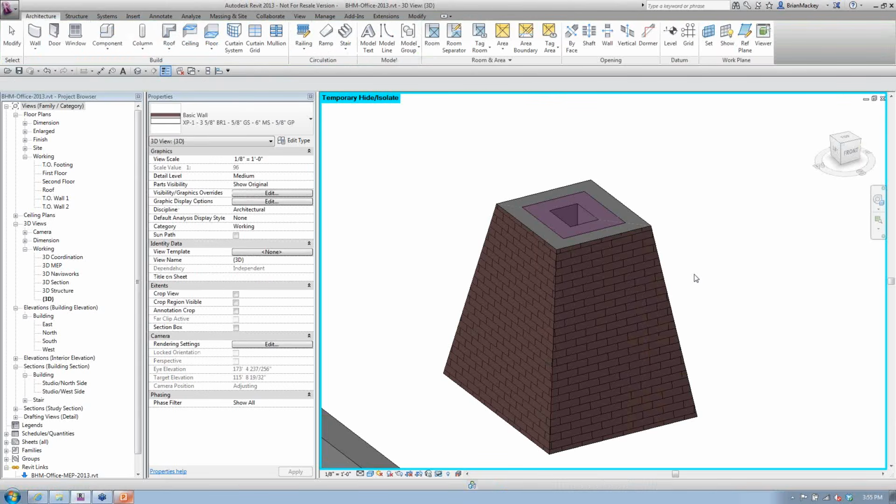And I could go model a structural column coming out of the middle of that. Okay, and Dale asks, if I go to town in Vasari creating masses, can I then bring it into Revit and apply walls, floors, roofs, etc.? Absolutely. So that's one nice thing: you're creating a mass family inside of Vasari, or even a project in Vasari, because you have projects in there as well. It's a simple RVT file, so you bring that RVT file into Revit 2013. You can then go do walls by faces, etc.